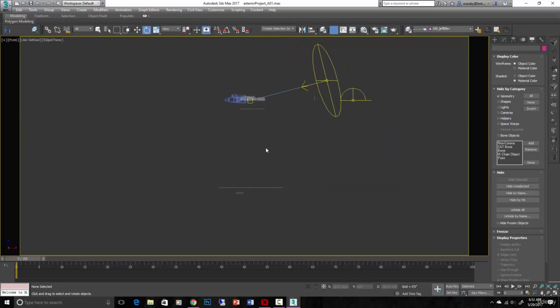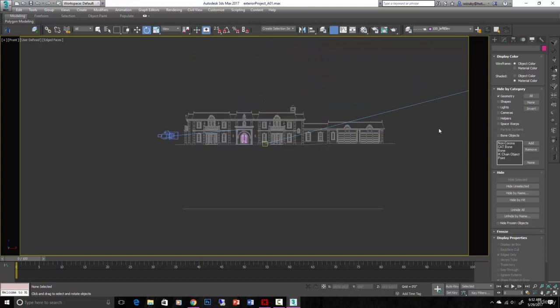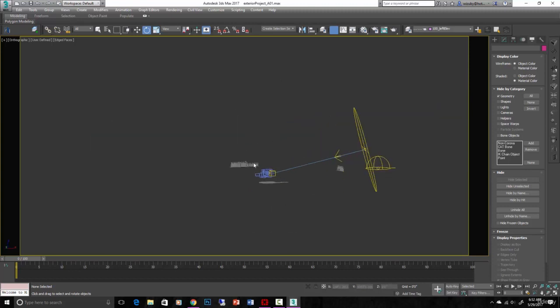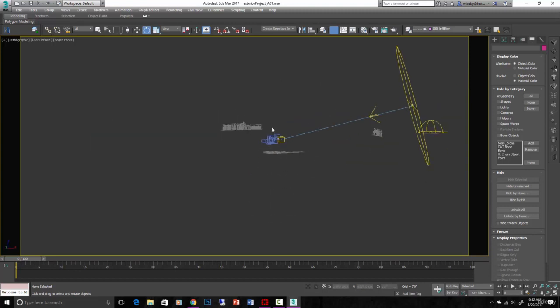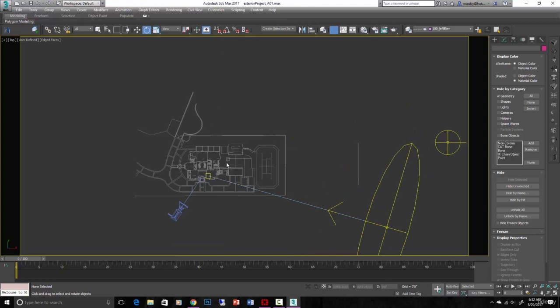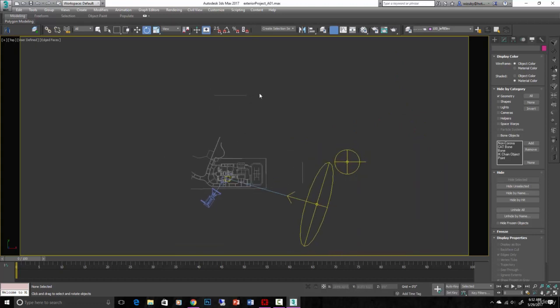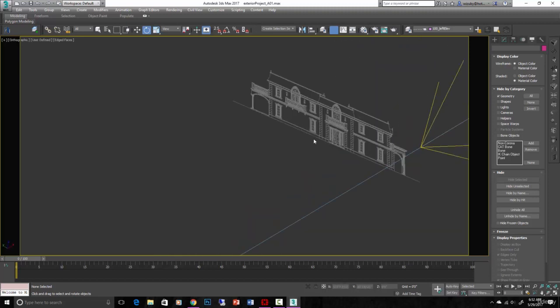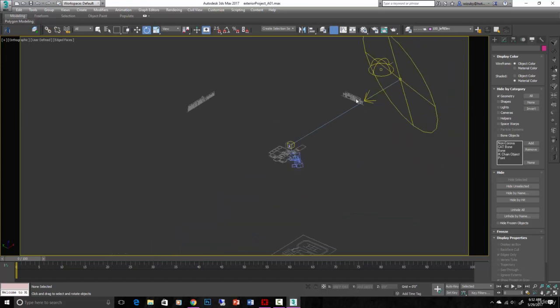With all the geometry hidden, we can now see the CAD that I've put in here, and I put it at orthographic view. So this is the exact front view. It looks like that. It's back there. 0, 0 is right in this area, and so you put it back behind 0, 0. If you look on the side, the other elevation I had to make, I took that left elevation and put it way over there to the right.